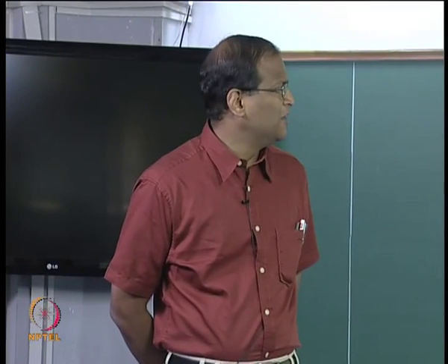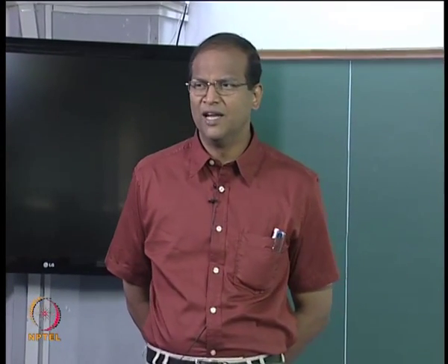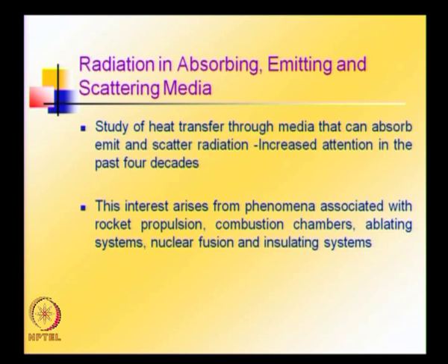So a participating media is an absorbing, emitting and scattering medium. You know that any particle which has a temperature more than 0 Kelvin will emit, that comes from Prevost's law. So it will emit. Absorption is something different for us. A gas volume absorbs radiation, that is, if 100 watts per meter square come in, what comes out will be less than 100 watts per meter square. It absorbs a certain portion of certain electromagnetic radiation, so that is absorption.